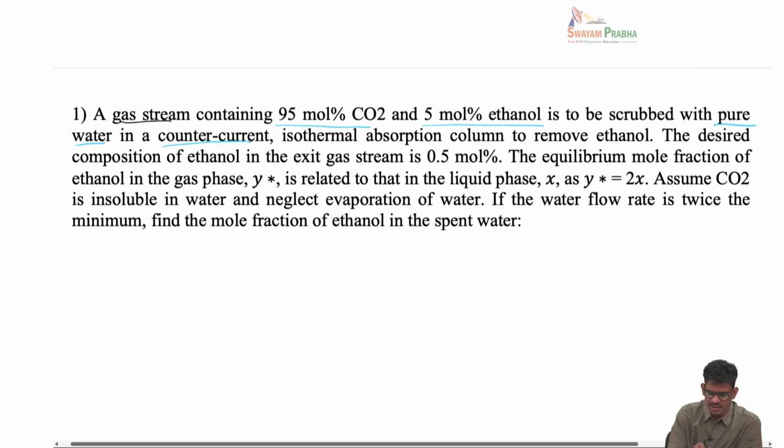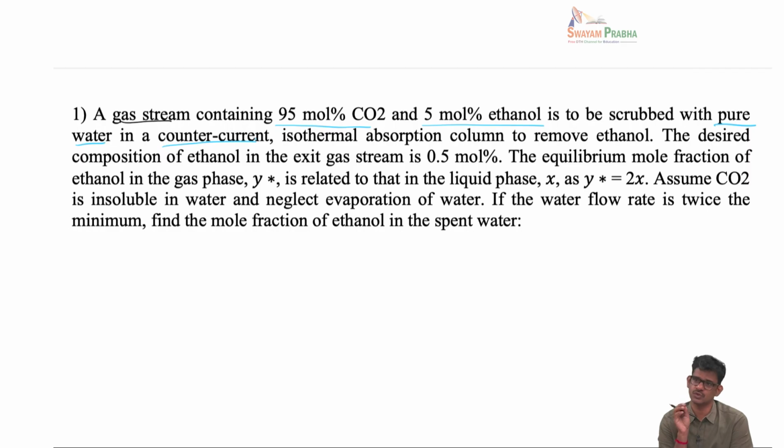Generally in other problems we assume CO2 is actually soluble in water or aqueous ammonia solution, etc. But in this problem the solute is ethanol and the liquid is water, and we are assuming only ethanol is transferring from the gas phase to the liquid phase. And here the counter current is explicitly mentioned. If it is not explicitly mentioned which operation it is, you are going to use counter current. If it is co-current, it will be mentioned.